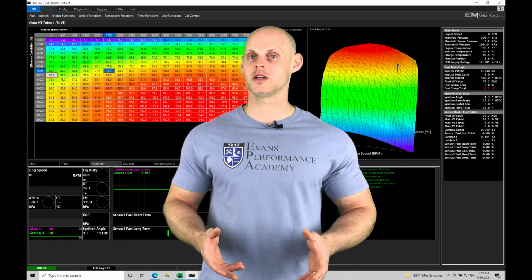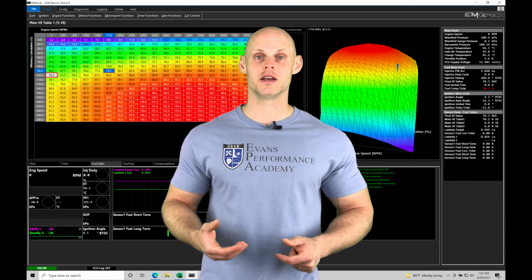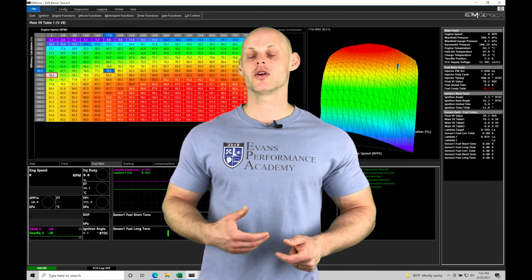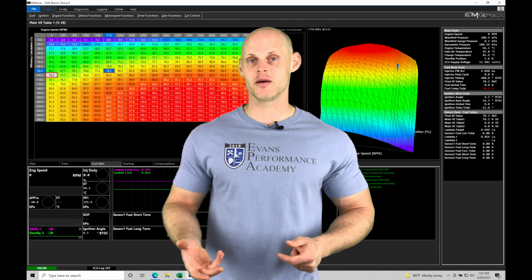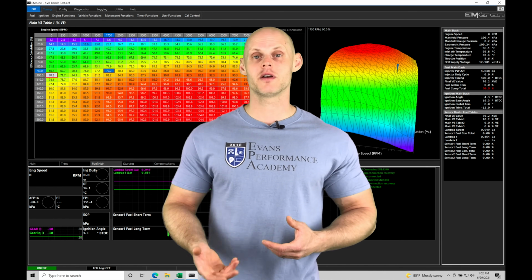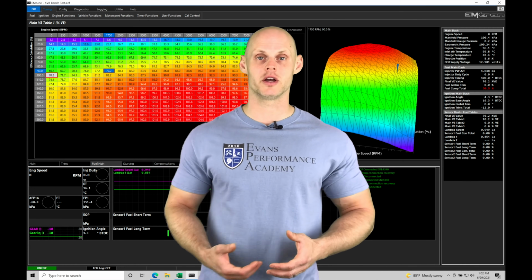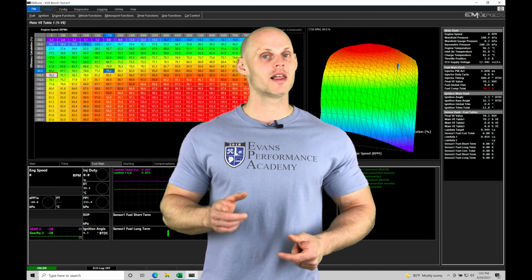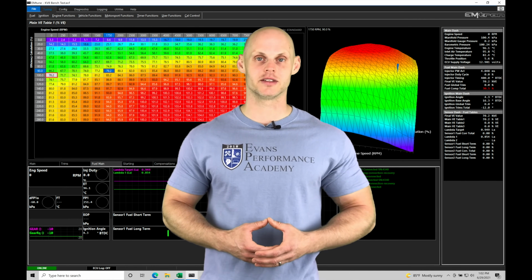There's going to be a whole bunch of things we go over here, learning the basic details of cam and crank patterns, learning how to work with an oscilloscope within the EMTune software so we can determine the actual pattern that we're working with, and other fundamentals such as a rising and a falling edge trigger. We have a lot to go over. Let's jump into our tutorial so we can check this out.